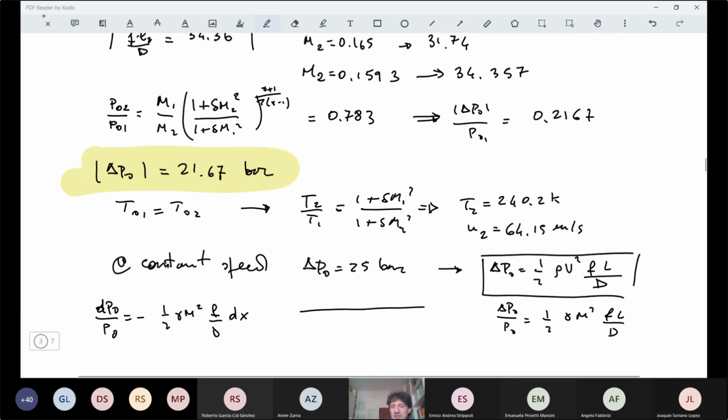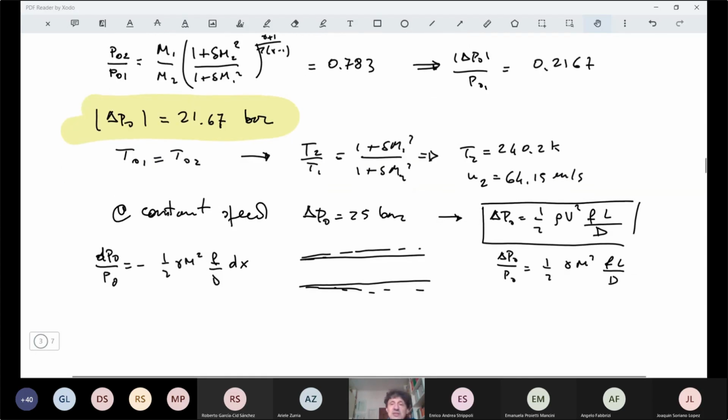So here we have a constant cross-section channel, you give some divergence that would slow down the flow, and that compensates the thickening of the boundary layer that actually occurs in the real case, and that would increase the velocity, as we have seen here by this expression.